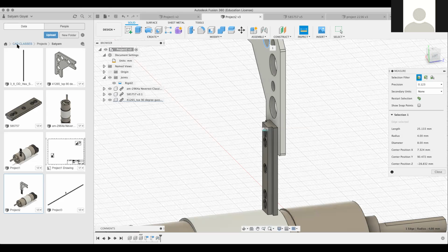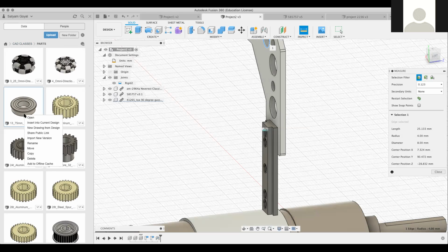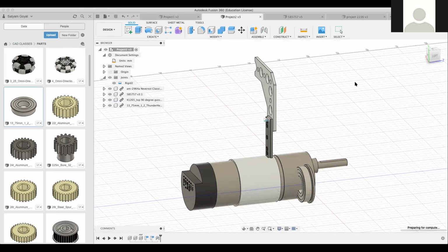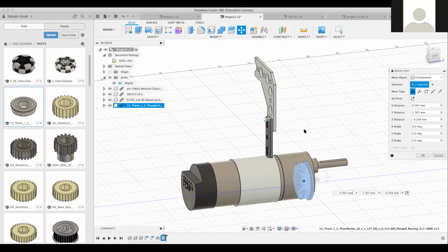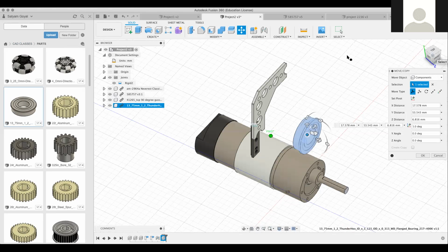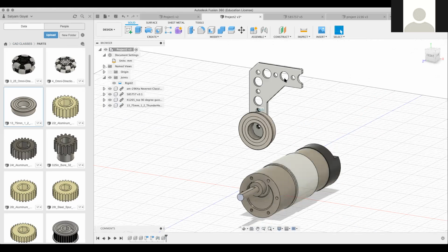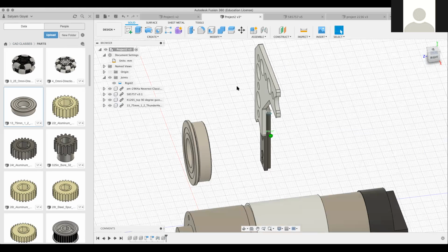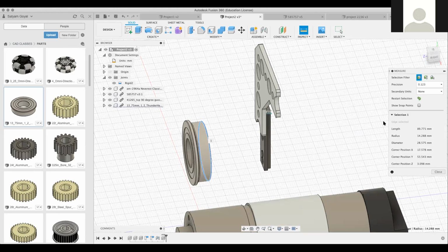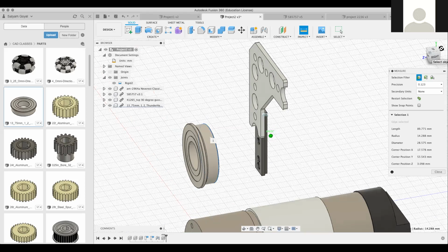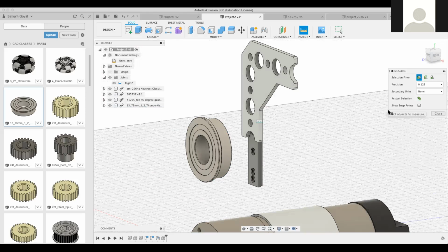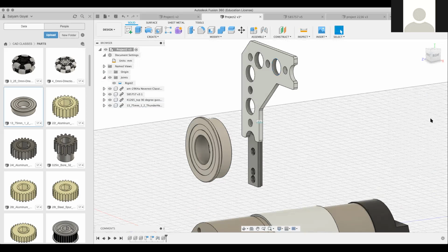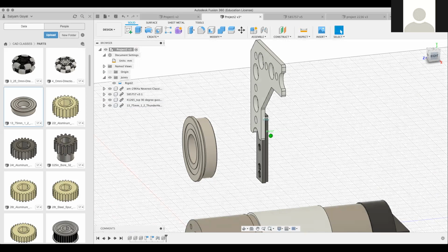A good example of this is, let's say I had this bearing here. All of this isn't applied exactly right now, but if I wanted to enlarge this hole to make it so this fits, then I could check the radius of this. So the radius of this, I know now it's 14.8. Now if I wanted to fit it inside here, I would check the radius of this, and obviously it doesn't fit. So that's why this function is really important. Again, just play around with this.